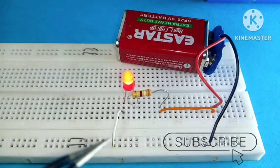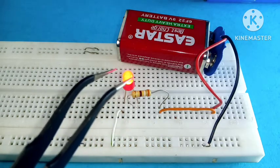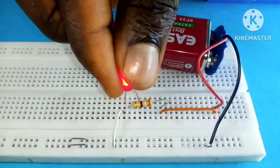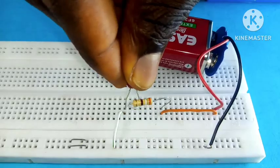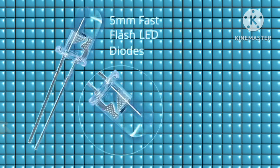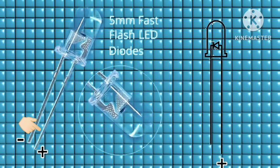So now you can see our LED illuminating in perfect condition with the 390 ohms resistor. If I swap the LED in reverse, you see it doesn't light up. If we look at this transparent type, we have the shorter lead, which is the cathode, and its lead frame called the anvil, and the longer lead is the anode, and its lead frame is the post.